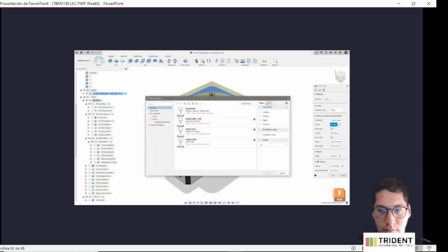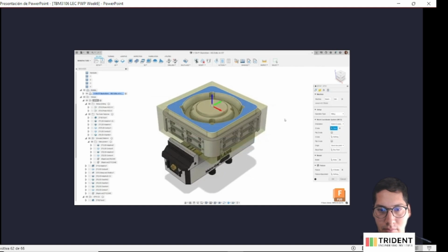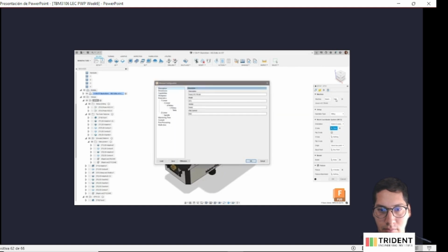dialog. This dialog contains a list of machines which have been utilized in various documents and locations throughout Fusion 360, as well as a list of pre-configured machines within an online Fusion 360 library. Clicking the drop-down link exposes the list of simulation-ready files. It's worth noting that this Fusion 360 library contains pre-configured machines and may not match the exact kinematics of the machine you have. Where a more accurate simulation is required, you will need to modify an existing machine or create a new machine to get a more accurate representation.